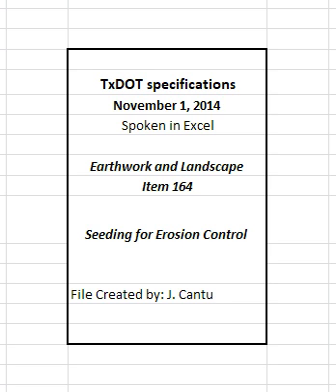2.4.2 Cellulose fiber mulch. Use only cellulose fiber mulches that are on the approved products list, erosion control approved products, http://www.txdot.gov/business/resources/erosion-control.html. Submit one full set of manufacturer's literature for the selected material. Keep mulch dry until applied. Do not use molded or rotted material.